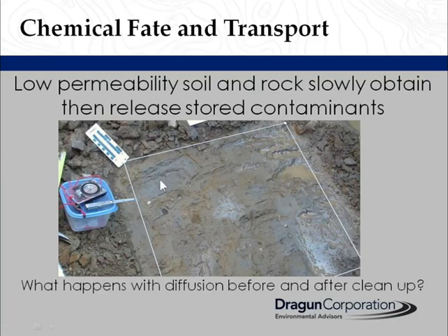This is a site where we were looking at manure ponds, and it's got clayey soils here, and this is where you would think that diffusion would be important, but you see these wet spots in the bottom. This clay soil is fractured and water moves up. So if there's contamination that is in the groundwater, it will preferentially move by advection through the fractures, but at the same time will be diffusing into the clay, the massive part of the clay.